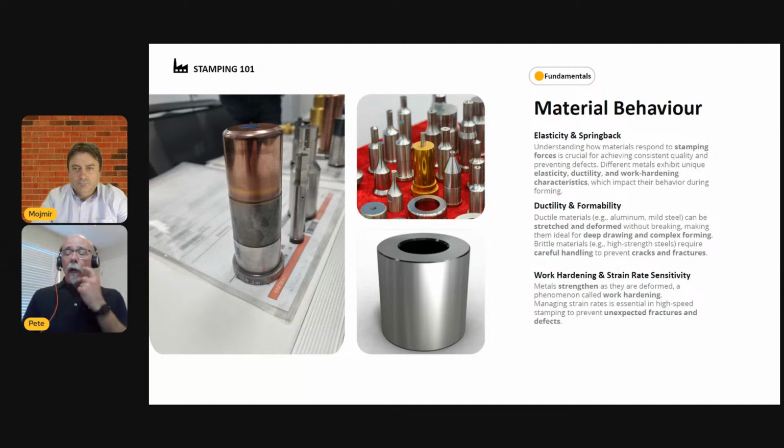Now, we relate work hardening to a material parameter called the N value, and some of you may be familiar with it. N values are typically small numbers. They may be anywhere from 0.18 to 0.24. I've seen some stainless steels with N values exceeding 0.35. These numbers may not mean anything to you if you're not familiar with N values, but I share that to make this analogy.